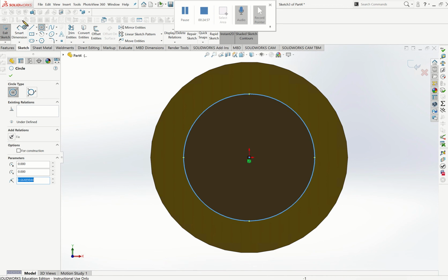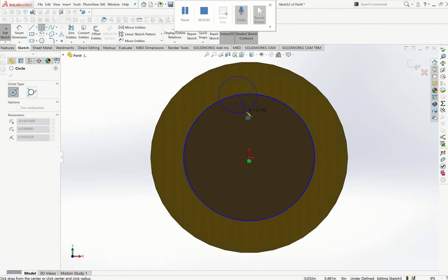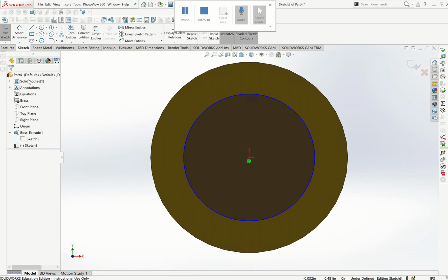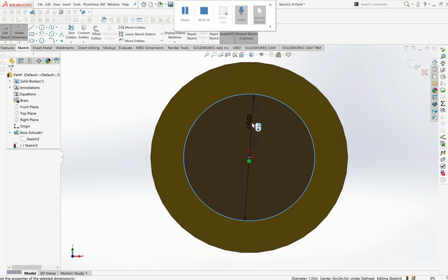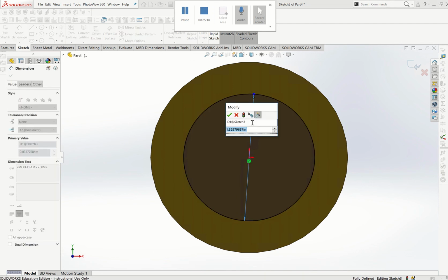And again, it's blue. It's not defined yet. I go to smart dimension and click on that. Again, didn't do it right. It seems to prompt me to draw another circle. You know what to do now, right? Escape. Then we go to smart dimension again, and click on that. Earlier, the radius was, I believe, 1. And now how about we make the radius 0.75.